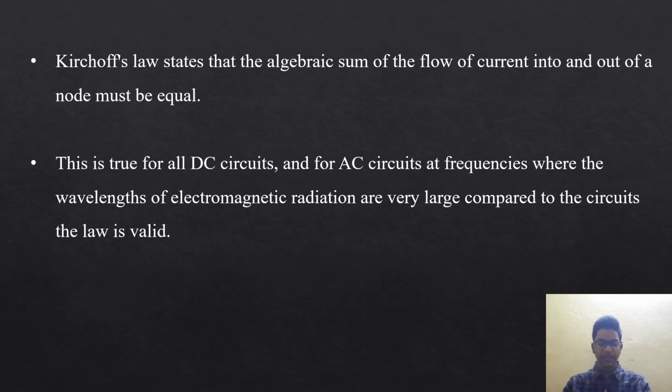Applying Kirchhoff's current law with sign convention, the practical application of KCL is to determine the amount of current flowing through an individual electronic component in a circuit. Kirchhoff's first law, known as the Kirchhoff current rule, clearly states that the amount of charge entering the node, the current incoming, is equivalent to the amount of charge exiting the same node, the current outgoing, when many branches of conductors meet at a particular node. The total sum of charge or current around the node is zero.